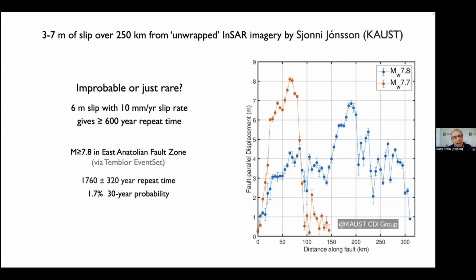And that's not quite a 2% probability in 30 years. So what's the answer to the question? It's rare, but it is not improbable. And thinking back on Quakecaster, you can see now there's always the possibility of yet larger earthquakes. And so we cannot eliminate that possibility. And if anything, even calling this a 600-kilometer fault is probably inappropriate because the fault makes kind of a left turn and becomes the Dead Sea fault zone. But these faults may not know that they have different names.